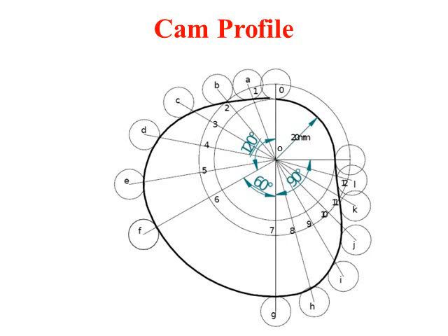Now as in this particular problem the follower is in line, draw a vertical line from O which passes through the base and the prime circle, such that it touches the prime circle at 0. So with 0 as the center, that is on the prime circle, draw a roller of radius equal to 5 mm. That is where the follower will be.